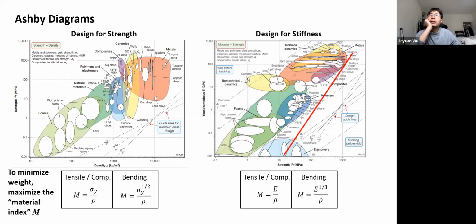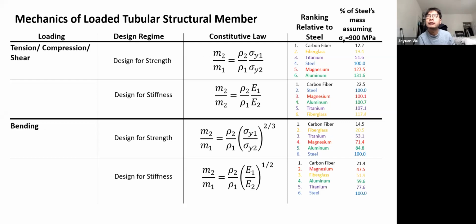Don, I have a question on that. Carbon fiber is incredibly good in tension, but is it as good in shear and compression? I was under the impression it's so directional that it wouldn't be as good. Right, that's a really good point, because you have to make sure which direction of shear you're using. In the case of shear you're going maybe perpendicular to the fibers. It's just a question of aligning the fibers for that particular load case.